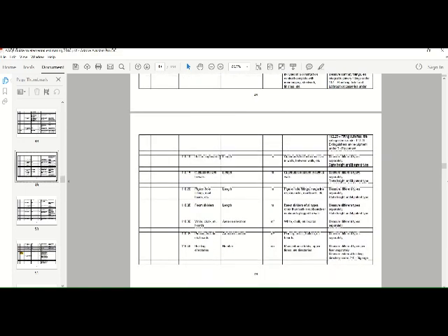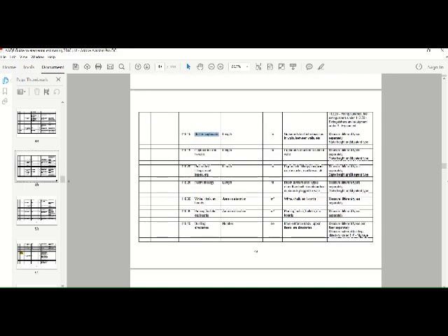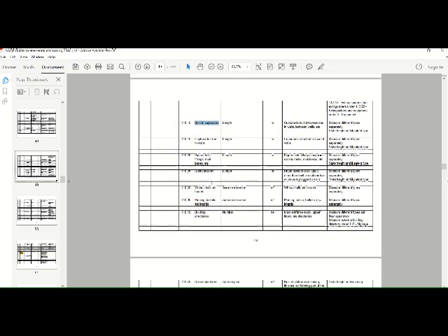Okay, so fittings like your cupboards, the main thing you need to remember here is that you should compare apples with apples. Wherever that's measured, it should not be included in any other rates that you used earlier on. Your cupboards usually is an easy item to measure. You just take a previous bill or cost of a building.